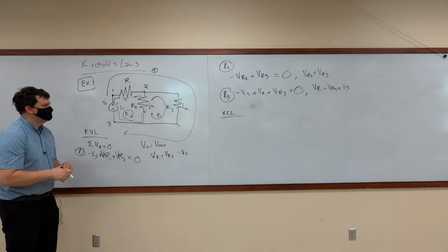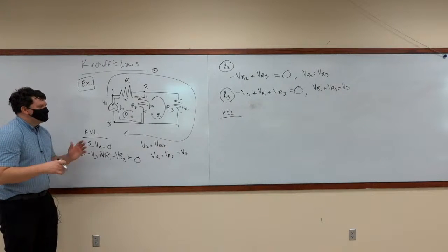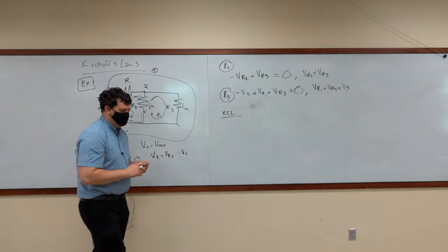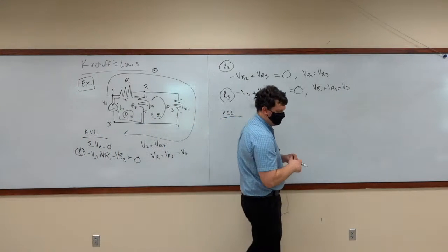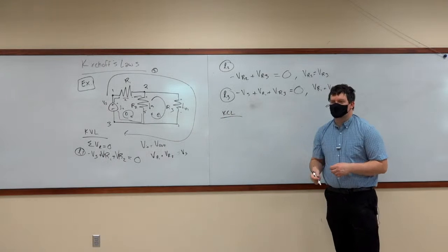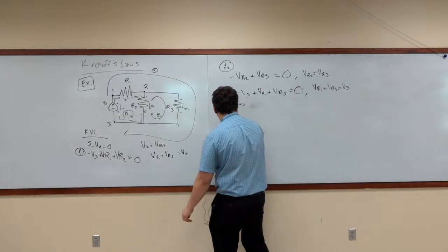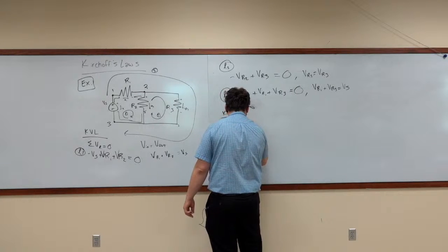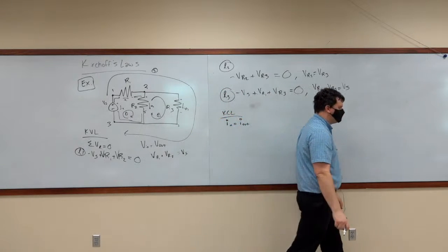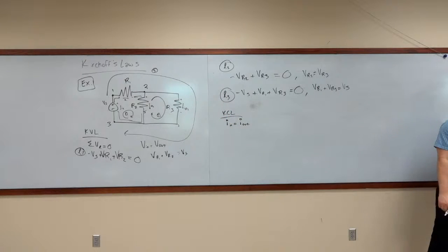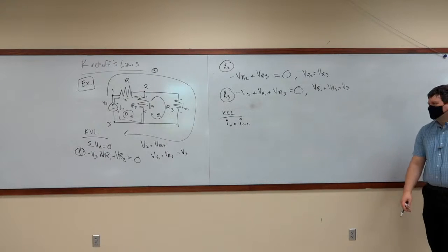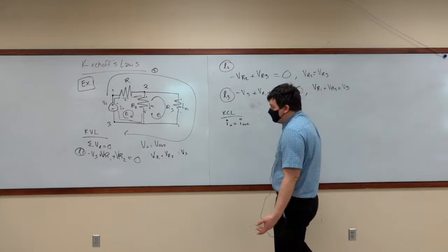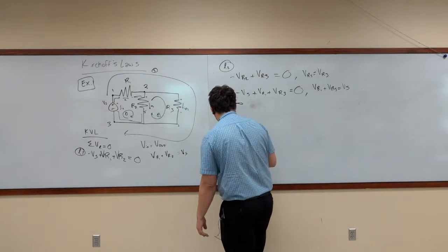All right. What's our equation for KCL? You already said it once, I'll just write it. We have the currents in is equal to the current out. Or we could do the sum of all currents into a node is equal to 0. Well, either of those work. They're the same equations. So what we'll do is we will look at every single node. We'll start with 1.